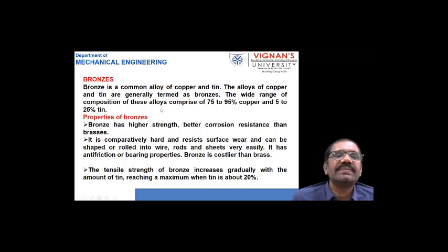The wide range of composition of these alloys comprises from 75 to 95% of copper and 5 to 25% of tin. So these bronzes have high strength and better corrosion resistance than the brasses. And it is comparatively hard and resists surface wear.